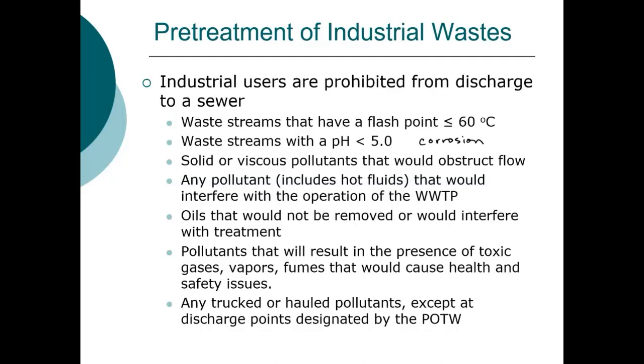That's a batch process. That means that there is a slug of pollutants entering the treatment plant. And for the most part, we're using microorganisms. That slug of pollutants can be toxic to the microorganisms, which means you upset the treatment plant and it's not working properly.